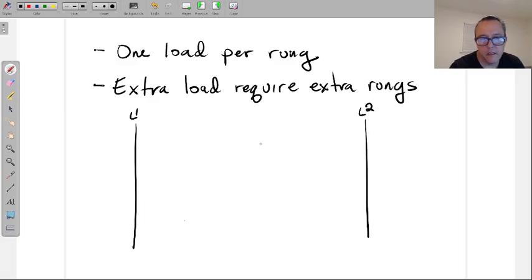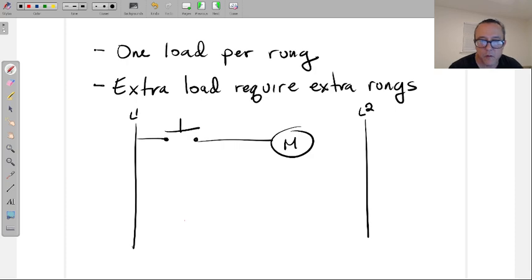So here's a second option. Say I got a push button, but now let's say I got a motor starter. All right, we know our motor starter now. At least we're getting familiar with our motor starter. Not going to worry about the overload right now. Remember what I said yesterday. Motor starters have auxiliary contacts on them. All right, again, motors, well, technically just the contactor, but let's imagine the overload was here, so I'm holding a motor starter. This is going to start the motor as soon as this gets power. Contacts close. Motor is now energized.